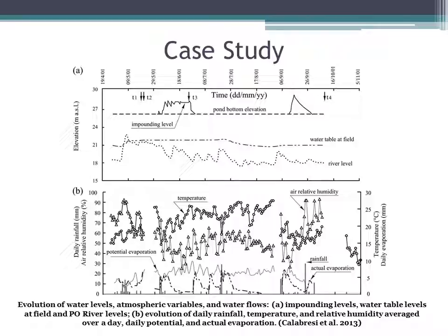These are necessary to calculate correctly the evapotranspiration. The potential evaporation has been calculated with the Penman-Monteith equation, while the actual evaporation has been calculated by multiplying the potential by a crop coefficient. Both are calculated according to FAO guidelines.